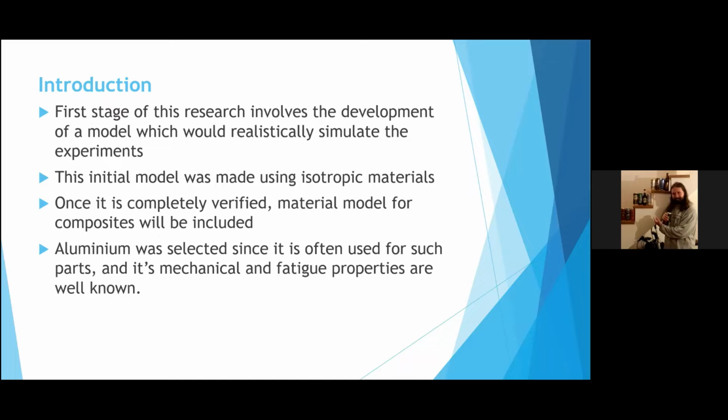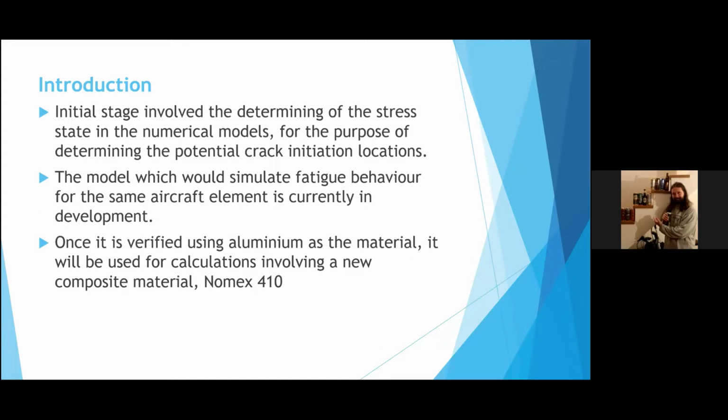So first, some simpler static models of the honeycomb mesh elements were made based on some of the experimental results so that we could determine the stress distribution under static loading, so to know where we can expect the fatigue crack to initiate. So the material we plan to use in the future is Nomex 410 paper and orthotropic composite. But before we can get to that point, we first need to verify that our initial approaches are correct by using simpler models for the fatigue behavior simulation in question.